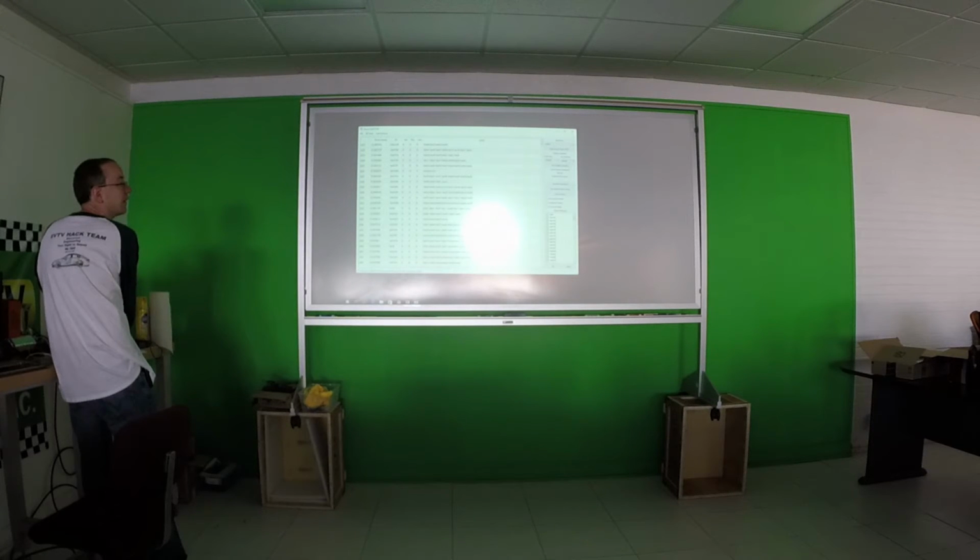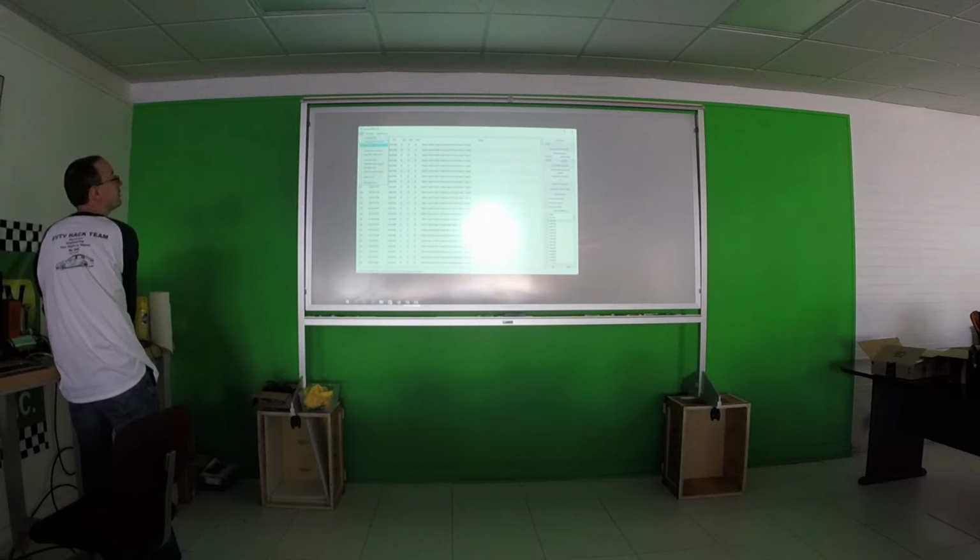I can go back here. Maybe there are just some I don't really care about. You can just pick out the ones you don't care about. Up here, there's functionality where you can save the filtered list. Let's say that I want to use a different program to do some analysis, or that I want to export to Excel just the 106 messages. You can select just 106, come up here, save filtered log file, and you'll get just the 106 messages saved to your log.